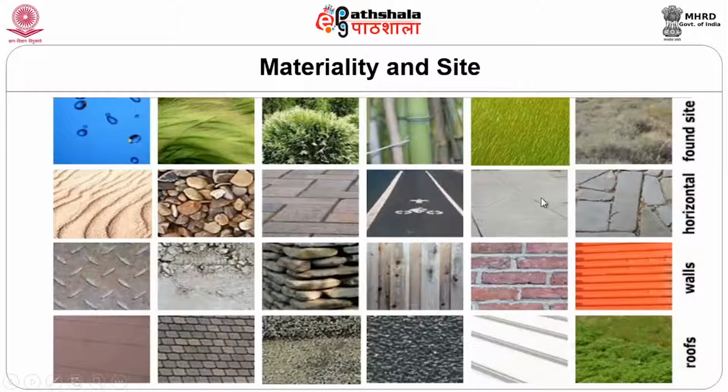Now, moving on to different kinds of paving in the site. It could be plain sand, pebbles, concrete, impervious concrete paving, or pervious concrete paving. You could have irregular stone paving, and finally tarring. Depending on the context and the scale of the site, paving devices can be chosen. A road has to be there unless it is completely vehicular traffic, as in some campus we are designing. If it's residential, let's make it pervious, so some amount of maintenance is reduced. At the same time, the water table can also be restored.